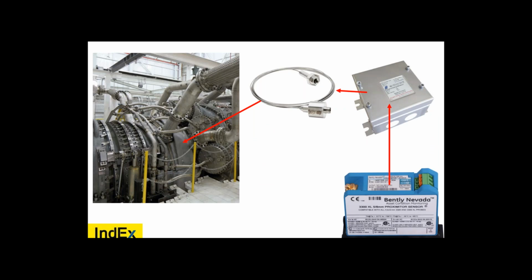Now I'll answer people's questions that they've proposed. Can we do self-declaration for EX nA, EX eC control panels without an ATEX certificate? Okay, that question's all over the place. nA panel, you could, if all of your internal components and the panel were manufactured before a certain date, let's say some date in 2018, and you assembled it. Then as a manufacturer, you can self-declare, declaration of conformity.